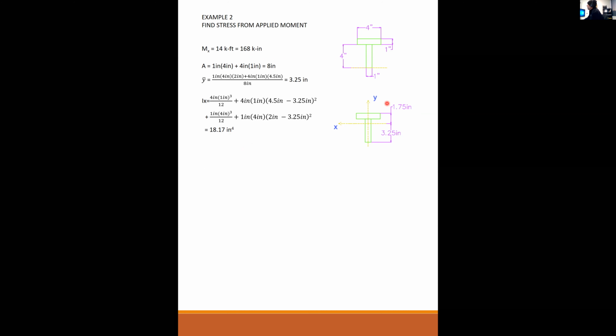Moment of inertia of the T section is 18.17. And that's the power of spreading these apart, getting the mass farther away from the centroid. It gives you more moment of inertia, more resistance, which of course is the reason why beams, particularly steel I-beams, have all the mass way far away in the flanges, as far away from the centroid as possible.